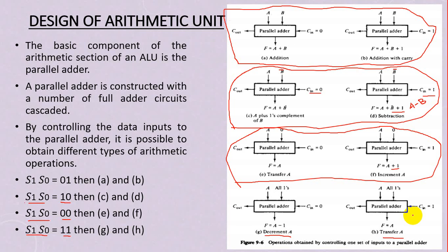So we need to design a circuit now. What will our circuit do? Depending on the selection input S0, S1, and carry in, the circuit will automatically modify this B. Because when we design, we don't need to manually modify B by ourselves each time, depending on the selection pin. We will design a circuit that will modify B depending on the selection pins S0, S1, and carry. So in this rough way, we modify B. Yes, modify B and modify A. We'll modify A during the logic operation, because we are doing some clever design, only a single set of hardware, the 4-bit parallel adder.